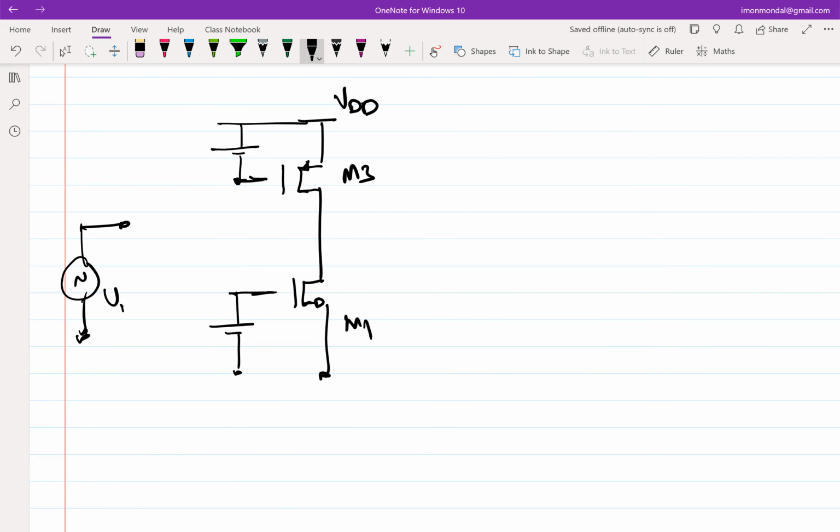I can use a capacitor. Also, I'll have to decouple this, right? Because if I keep this VGS, if I use these batteries, then my VGS will never change, right? So I have to decouple. I can use a capacitor and all those things. But yes, you can in fact do that, and that is done many times.